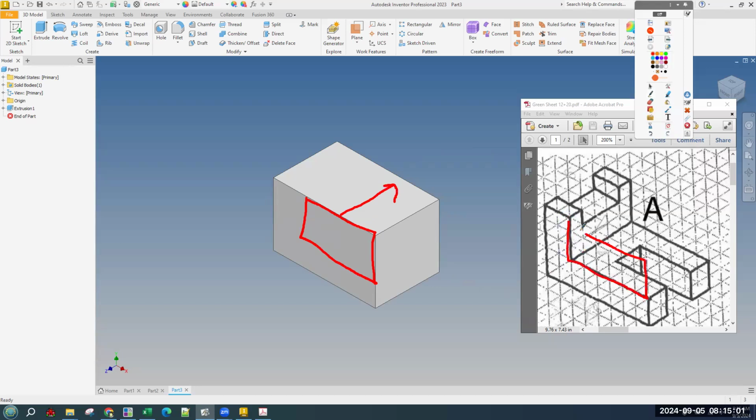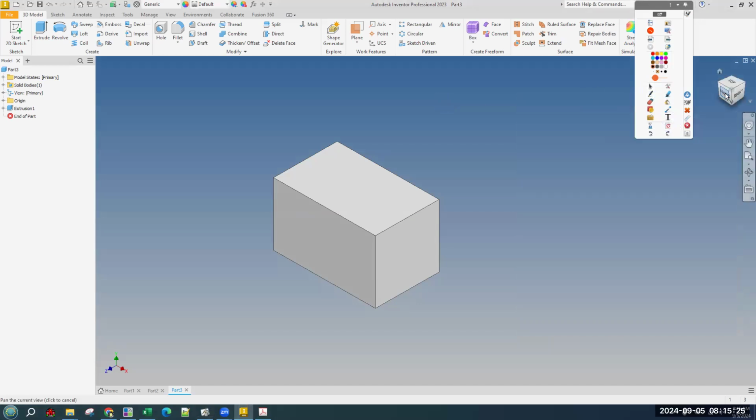Now, we can figure out this dimension, which is 6, and this dimension that is 3, and make a 6 by 3 rectangle here and cut it across. But what we're actually going to do is dimension the remainder. Whatever size our rectangle is, it doesn't matter so long as 2 inches are left this way and 2 are left this way. So that's going to be 3-click dimensioning.